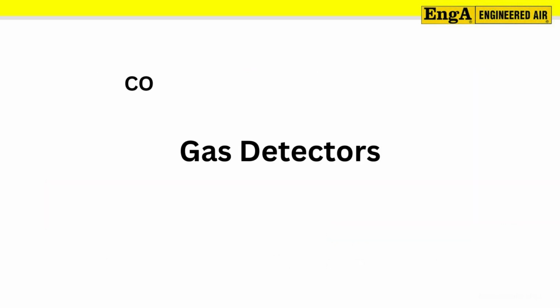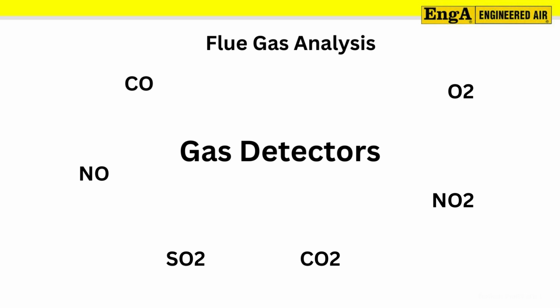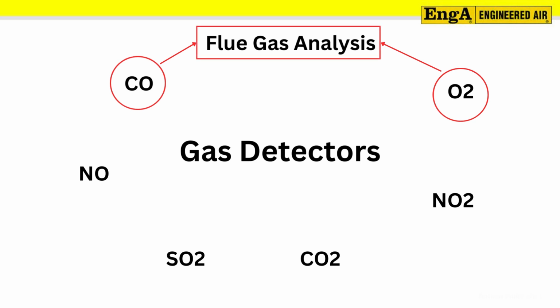There are different types of gas detectors available, therefore check if your analyzer is intended for flue gas analysis. Be sure to periodically send your combustion analyzer to a certified instrument calibration facility to verify its accuracy.